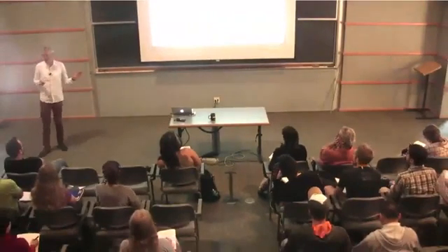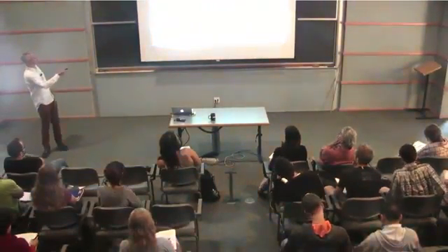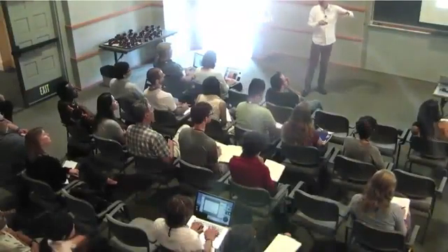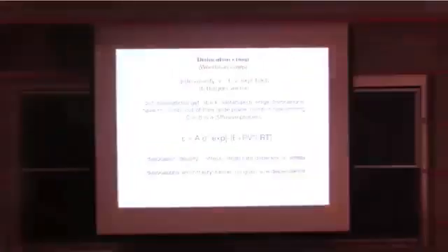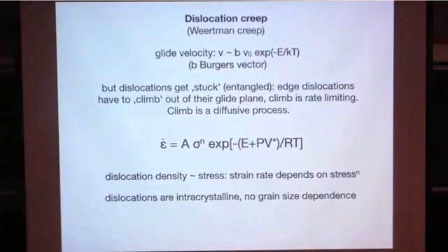That's a great question. So again, you can look at a velocity with which the dislocations move in the crystal lattice, and you can derive a first principles equation looking at dislocation deformation, and you get different values for the n depending how you think the dislocations are generated, dislocation sources and so on. It turns out, though, that most of the models arrive at whole numbers for this n. If you do the experiments, it turns out that n doesn't correspond exactly to any of these models.